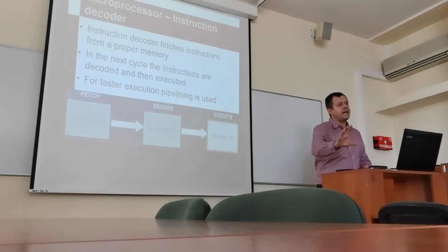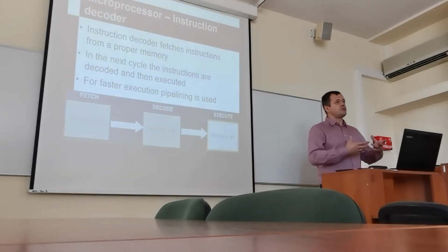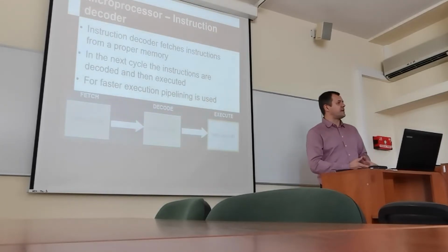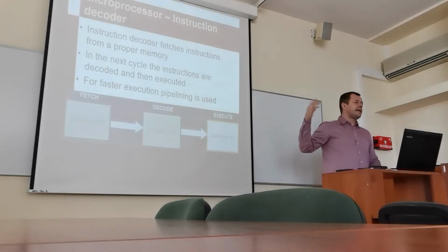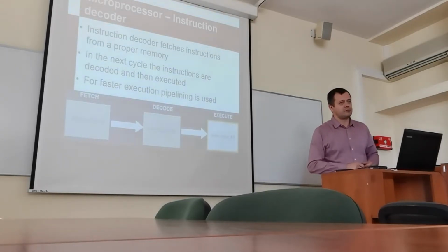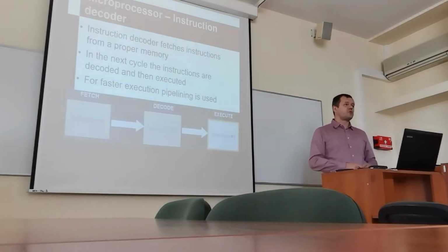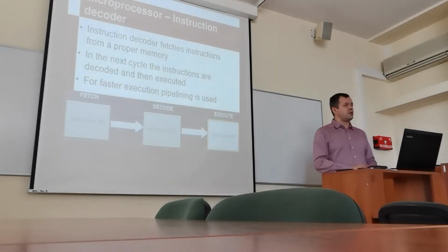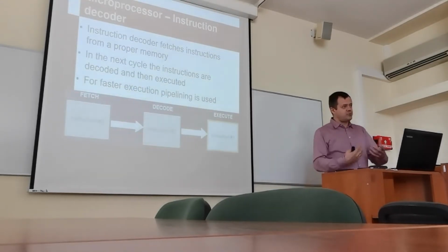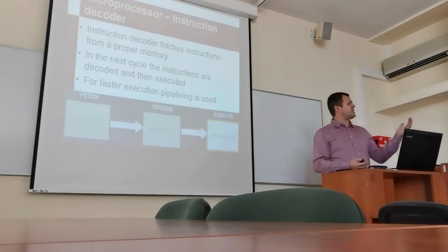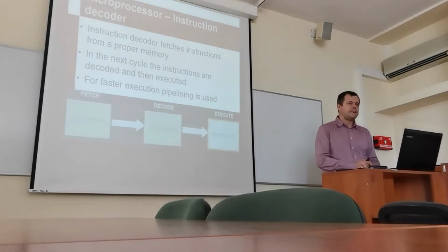That's where, for example, cache begins, because the cache is a kind of fetch supporting memory, which speeds up the fetching process. In case of hundreds of megahertz microcontrollers, and in case of parallel operations or so-called superscalar processors, the fetching becomes the element that has to be improved and has to work better, not just simply get 1 byte of data from this cell.